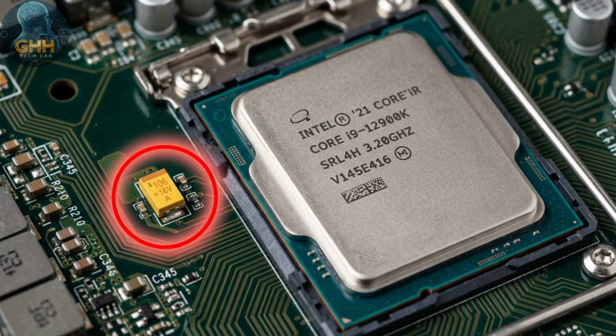For high reliability in dense spaces, engineers turn to tantalum capacitors. These are polarized solid-state components that offer massive volumetric efficiency without drying out like aluminum. But beware, they do not tolerate voltage spikes. Overvoltages can trigger a violent, self-sustaining exothermic reaction, meaning they catch fire.